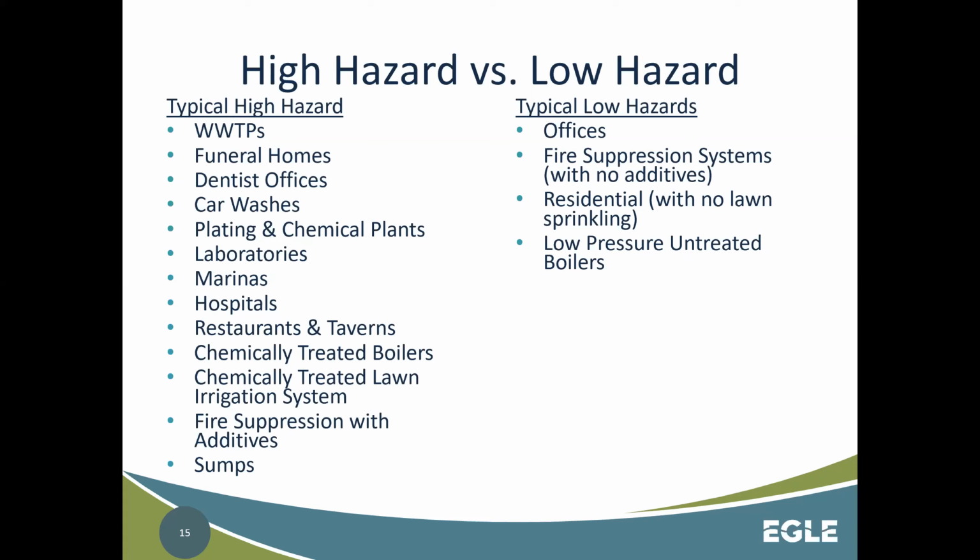Sumps have been considered a high hazard now because everyone and their brother is now installing what's called water assisted sump pumps, which is a sump pump that runs on the water coming from the water system, because the water is always supposed to be flowing in municipalities because of backup power. So a water assisted sump pump, which is hooked to the water system and runs off the water system, is also put in a sump. Those are high hazards. Those require an RPZ. So that is something that you as cities need to start looking for. They are becoming more and more common in these houses, and they're hooked directly to your water system.